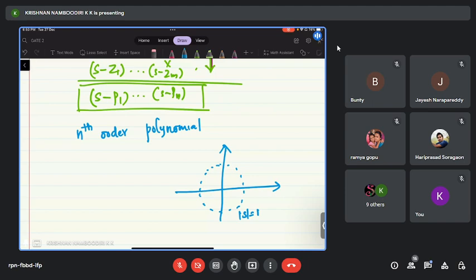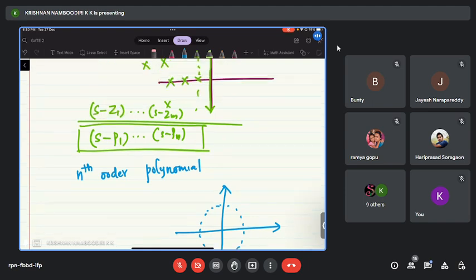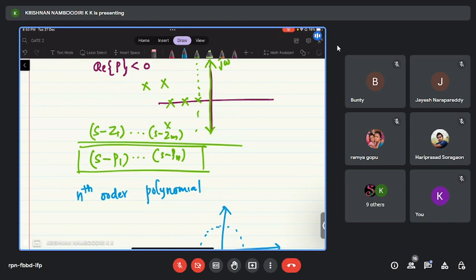Why is causality important? Causality is important because the signal cannot be a left-sided signal. If a system is said to be non-causal and stable, then everything will be reversed, in the sense that the j omega axis must still be contained in order to have stability. Non-causal means the signal is a left-sided signal. Then all the poles must lie on the right side of the j omega axis if it's a non-causal system. Okay. Is that understandable? Is that clear?